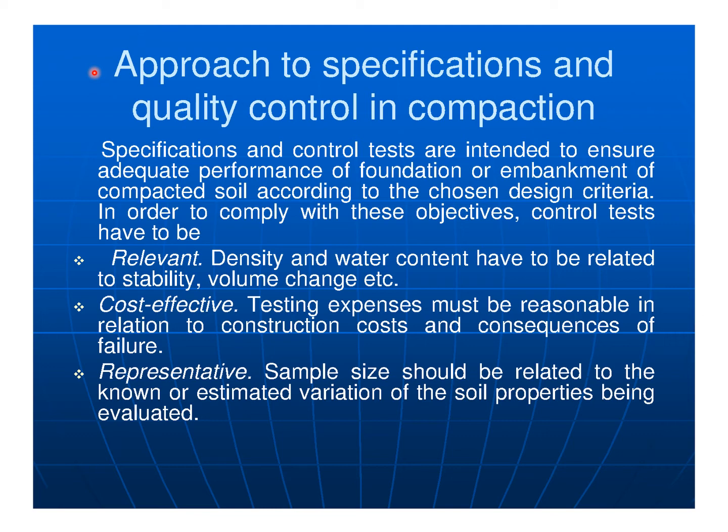Approach to specification and quality control in compaction. Specifications and control tests are intended to ensure adequate performance of foundation or embankment of compacted soil according to the chosen design criteria. In order to comply with these objectives, control tests have to be relevant, cost-effective, and representative.